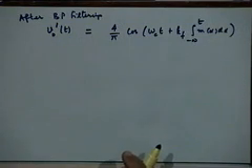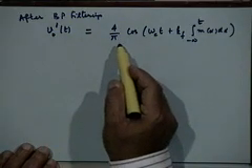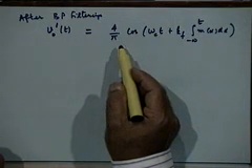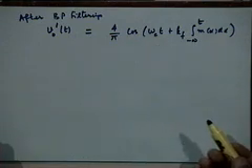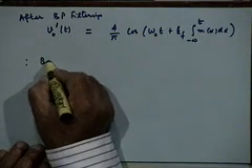So, as you can see, independent of what is the value of A of t, right, the output has a fixed amplitude equal to 4 by pi, right, and your FM signal, the FM variations remain intact as before, and that is how a band pass limiter works.